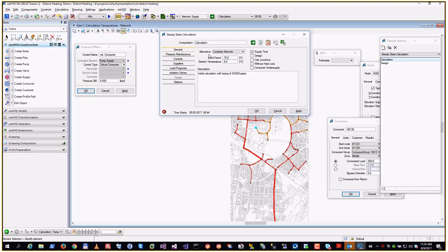Okay. Normally you deal especially with load factor and temperature setup. Then you have to have one pressure maintenance to define a point of fixed pressure in the system. And from the plant, when you operate it, the pressure maintenance is typically located where the supply stations are. You have the expansion vessels and the pressure maintenance, and it's nothing we compute, but it just gives you a fixed point of pressure.